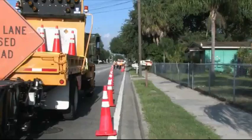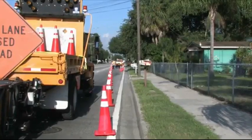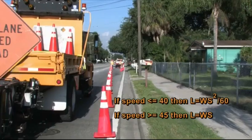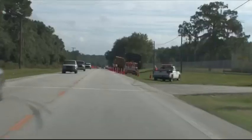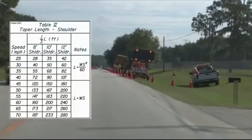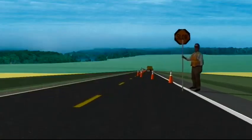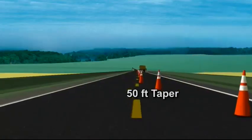Let's briefly review tapers and taper lengths. Where traffic on a multi-lane highway must merge, the required length is a function of the speed limit and the lane width. When working on a shoulder, check Index 602, Table 2 to determine the required taper length. When traffic is on a two-way road and it is reduced to one lane, a 50-foot taper is needed.